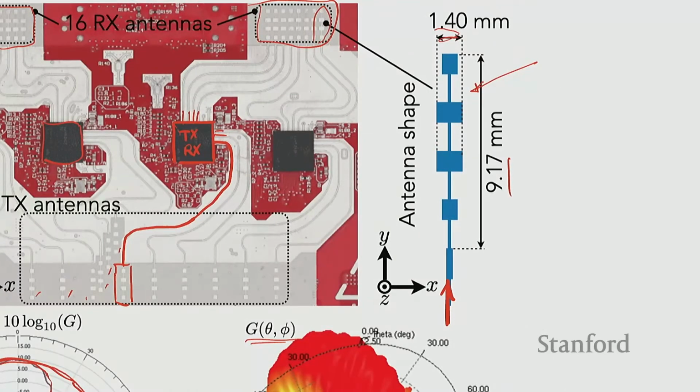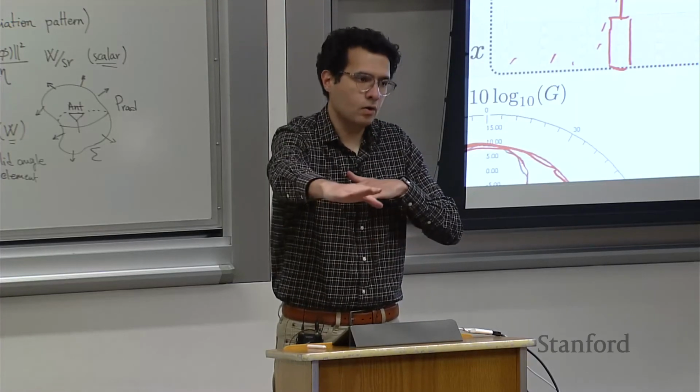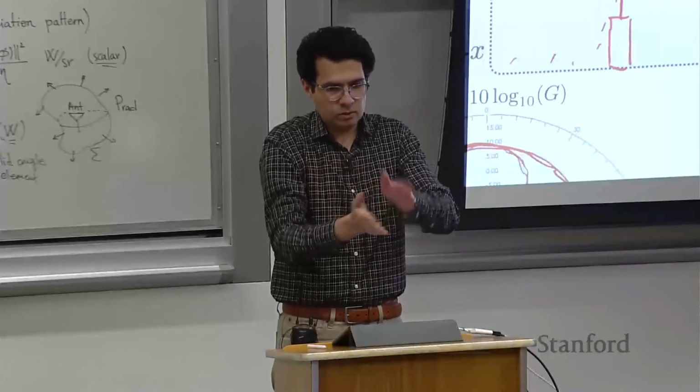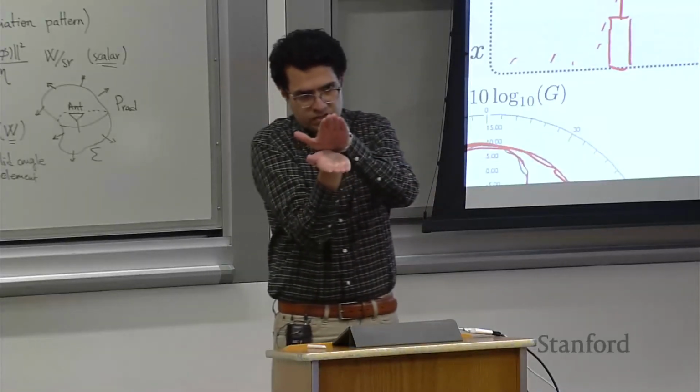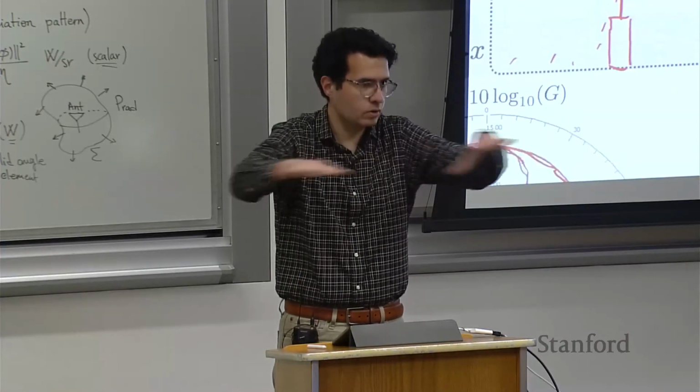And why is that? This specific radar is designed for automotive applications. It is a reference design to be mounted on cars, for applications like self-driving cars and things like that. So in the environment this radar is going to be used in, what do you want to sense? It's a car on the road. You're not interested in things in the sky. And below you, there is the road. You're not interested in things that are under the surface of the road, right? That's why you want to focus most of your energy vertically in a very narrow beam, so you only see cars and buildings and things around you, around the horizon.